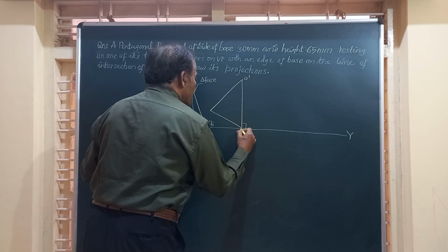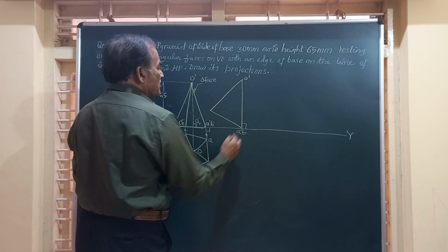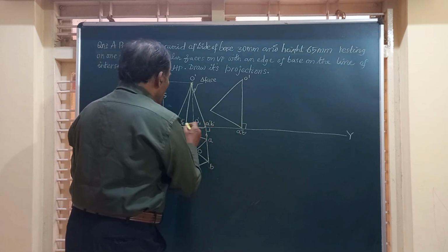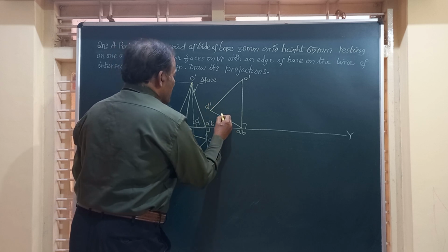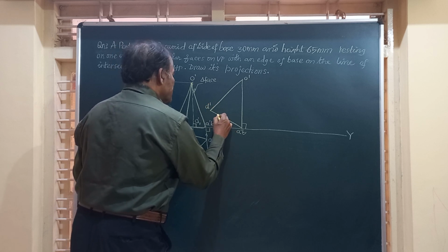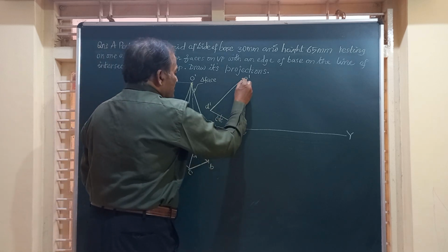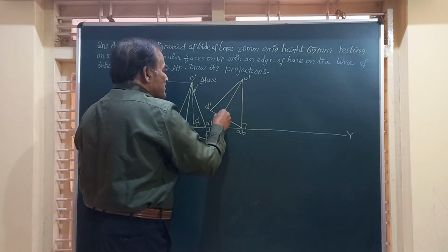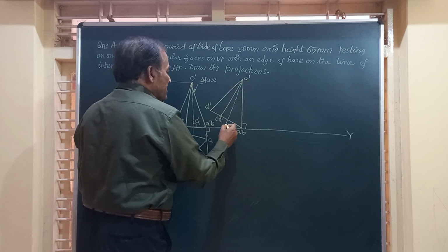So this is recorded as A dash, B dash, that is normal to HP, and we will mark the corresponding points. This is D dash, and here you get C dash, E dash. Simply you can take this measurement and mark it, friends, and we have to join that to this. Then you have got this axis O dash, O1 dash.